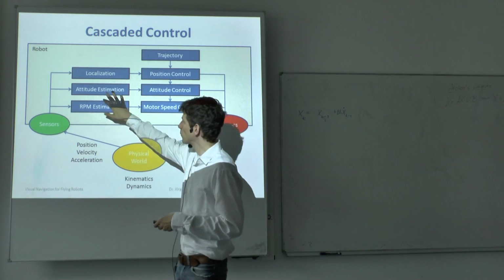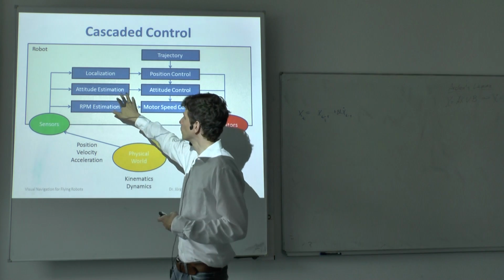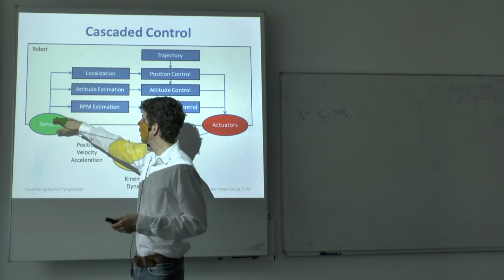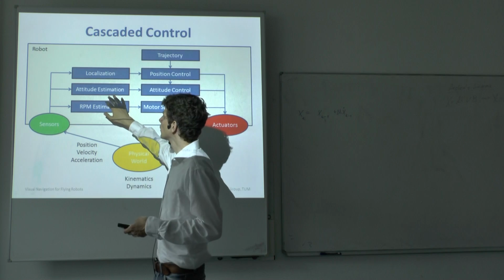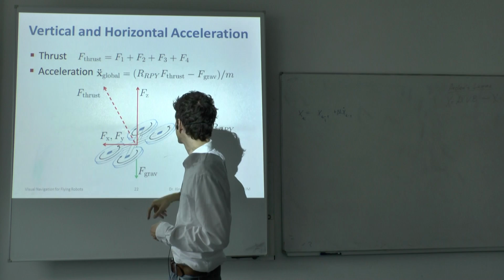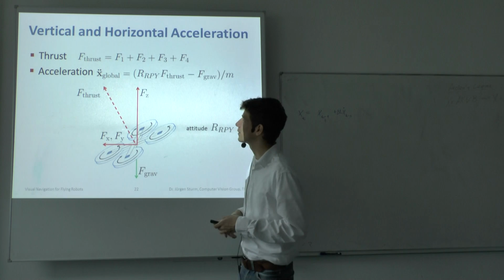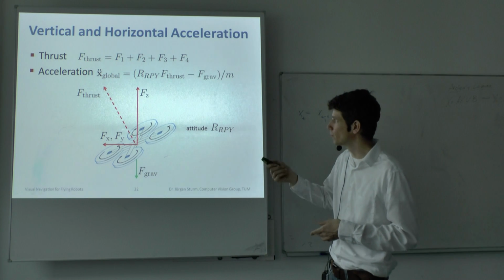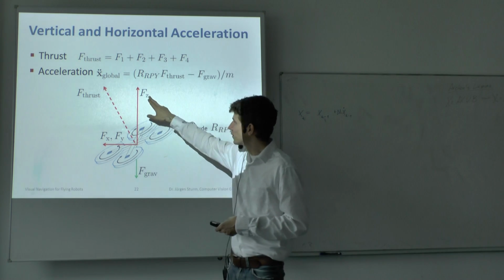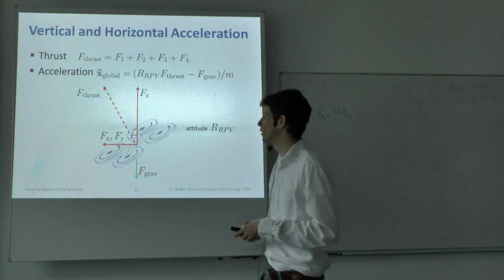And yeah, exactly. So there is one part here on the attitude estimation that we've discussed in principle last week, where we get in the measurements from the gyroscopes and the accelerometers, integrate them up either in a Kalman filter or in a simpler framework, and that will spit out this rotation matrix that we need to compute the forces in x and y direction, and which total force we need to put on the motors to keep the thrust force equal to the gravity.